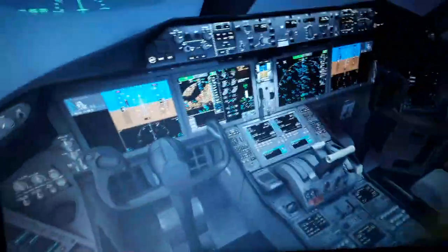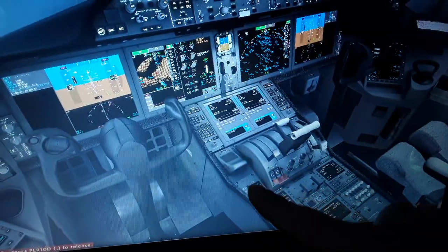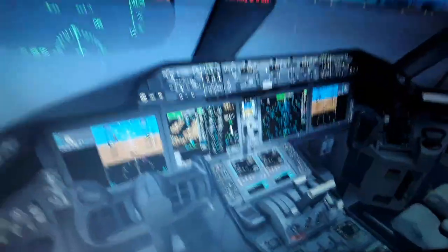So we have also the horizontal trim stabilizer over here and here. For every aircraft we can trim the horizontal tail of the aircraft when we fly. This is a fly-by-wire aircraft. It has its flight control computers. So when you move the yoke on the Airbus aircraft, you have the side stick. You give a command to the flight control computers in the air, depending on the mode you are in, like the flight mode or the ground mode or the roll mode. So we have the normal, the alternate, and the direct mode of the flight control computers, both in the Boeing and the Airbus aircraft. Also we have the mechanical backup.